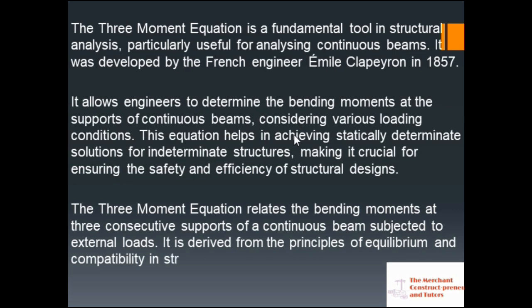I remember explaining what statically determinate and statically indeterminate structures stand for, what they mean, and how we can analyze them. For statically determinate structures, we can only use equilibrium methods to solve them, while for indeterminate structures we have different methods: the moment distribution method, the three-moment equation, and other methods. So here we are using the three-moment equation that was developed by the French engineer Émile Clapeyron.